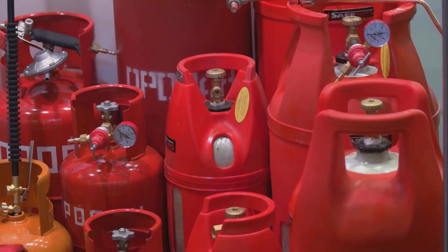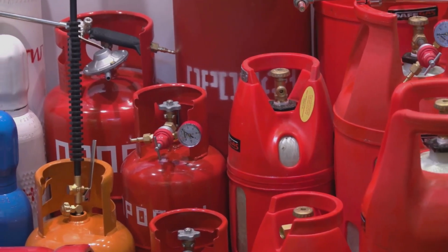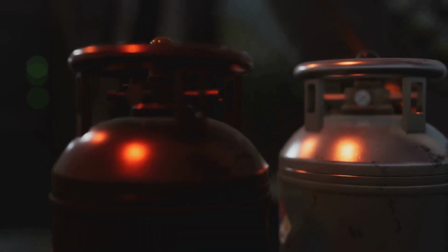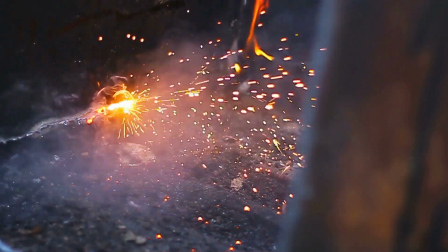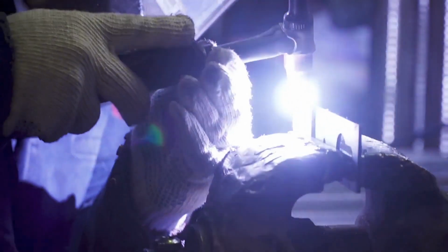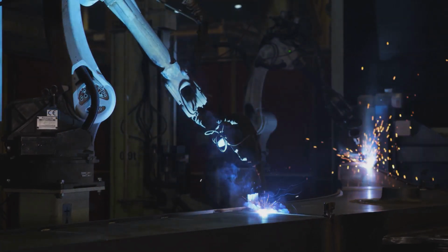Although argon is often used as a pure gas, it is also frequently mixed with other gases to tailor its performance for specific applications. For instance, in welding, argon may be combined with small amounts of carbon dioxide, helium, hydrogen, or oxygen to adjust arc characteristics, improve penetration, or influence bead appearance. These mixtures allow for flexibility in working with different metals and thicknesses, helping operators achieve the best balance of quality and productivity.